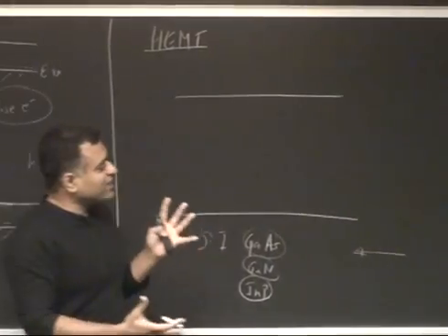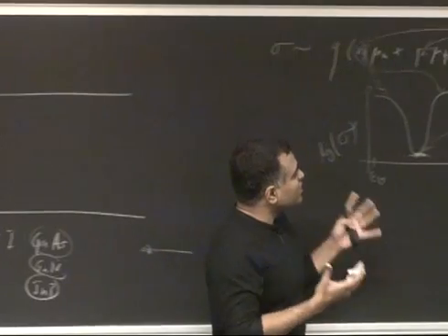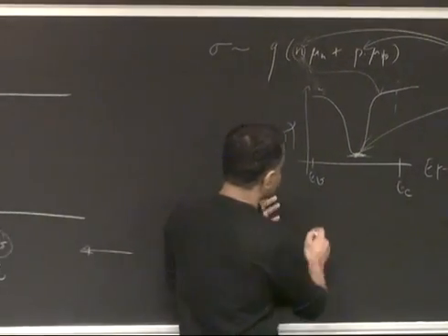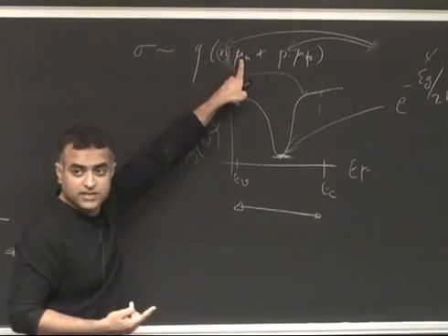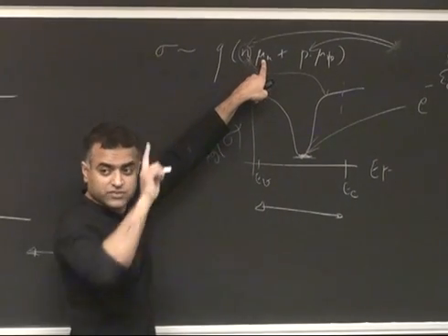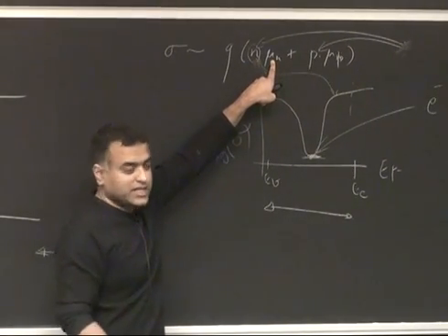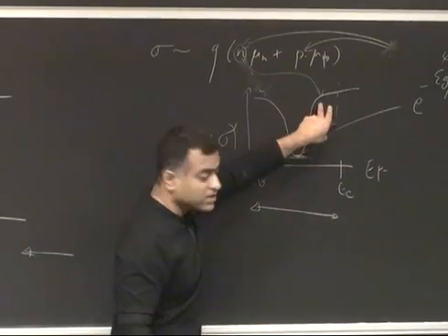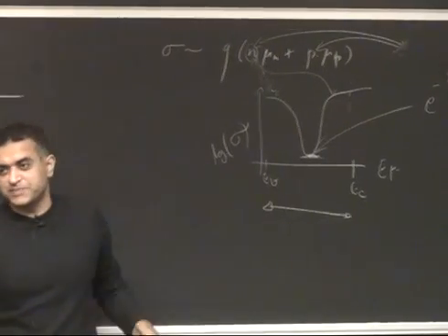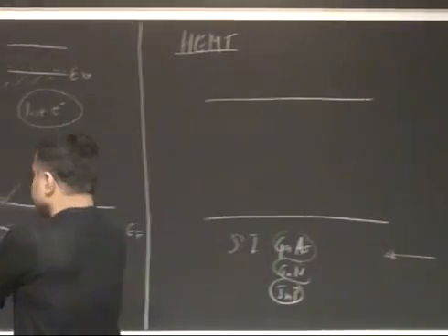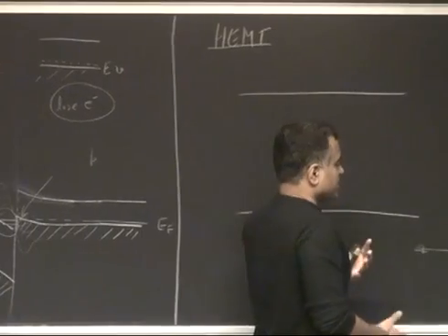So the trade-off is, the same semiconductors which have a very narrow band gap give you a very high mobility, right? The narrow band gap semiconductors give you very high mobility. But then you see the problem: when you're going to turn it off, it's going to have an issue. So if you're using it as a bulk material, and it's doped one type, N type or P type, whatever, right?